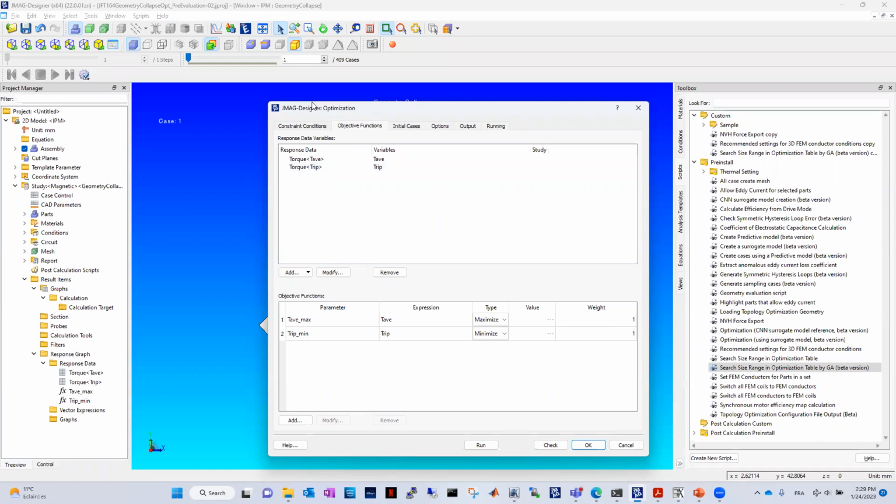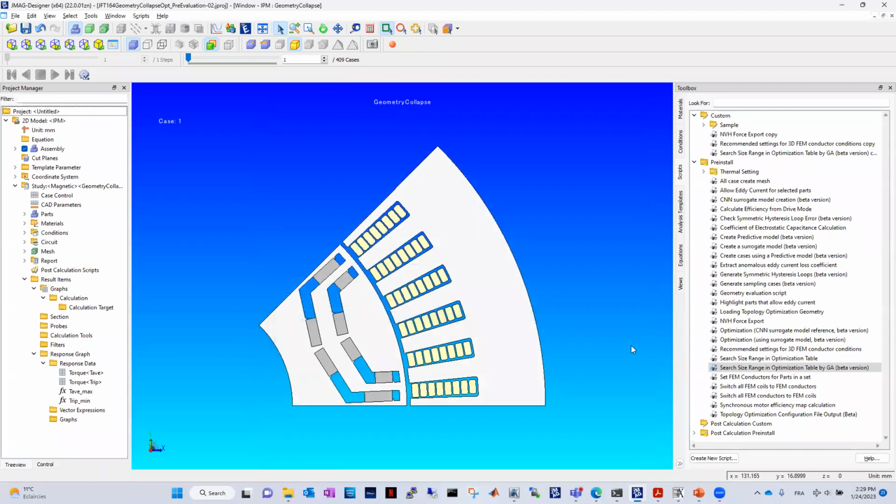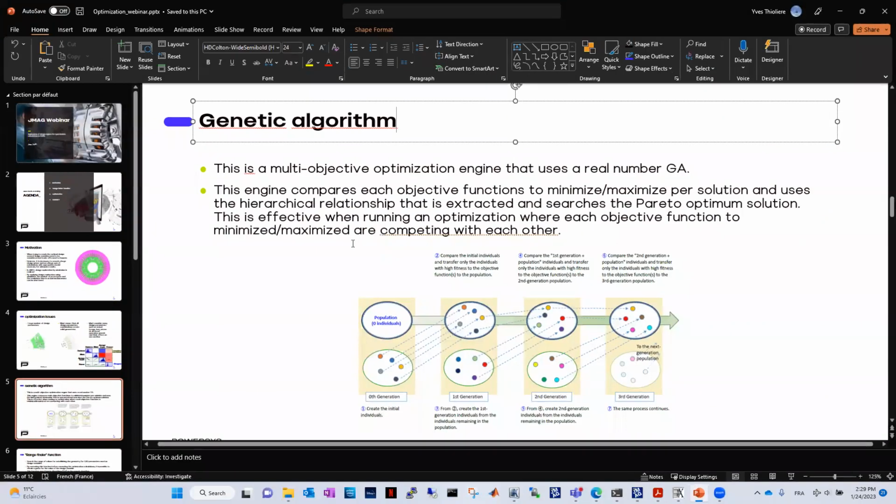In the objective function, in the main optimization process, yes, you can put some weight and you can prioritize if you would like the torque average to be more important than torque ripple, for example. So yes, you can do that. But the one I'm presenting now, which is used in the rangefinder, is not dealing with the main objective of the optimization. It's just checking if it's valid or not valid from the shape point of view.